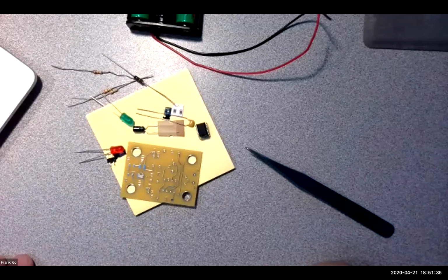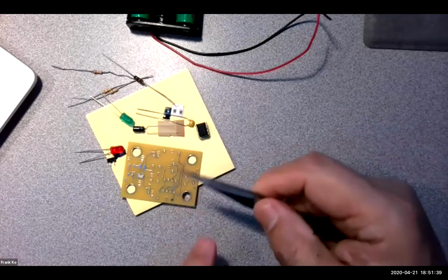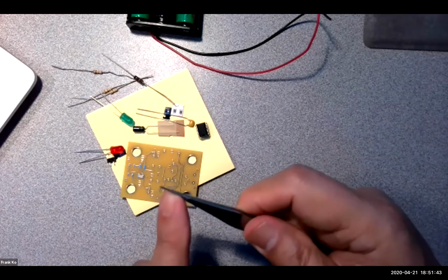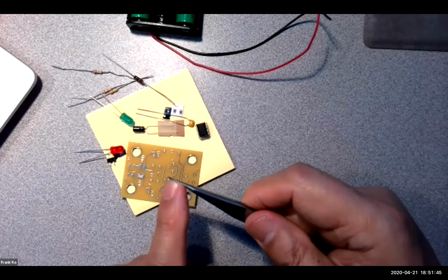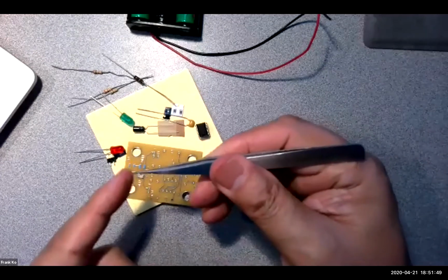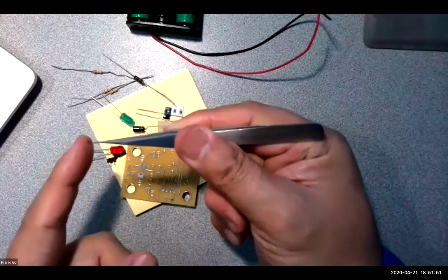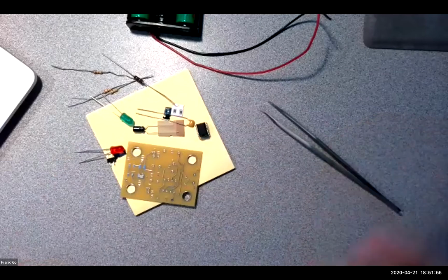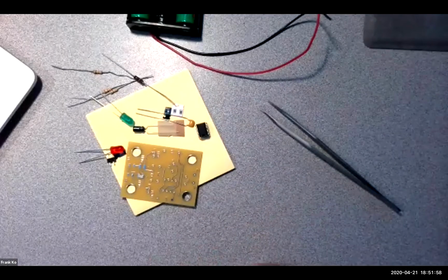Okay, good questions. I appreciate that, Brandon. So normally we use the shank. In this particular case, we will continue to use the shank of the soldering iron, but very close to the tip for most components. And then for the LED, for the surface mount devices themselves, we will use the very tip itself because the point of connection is so small. Any other questions regarding the kit?